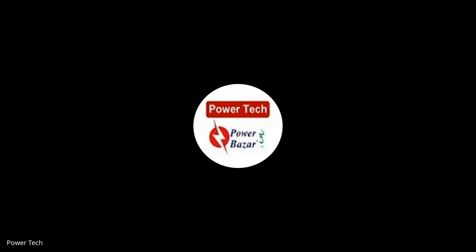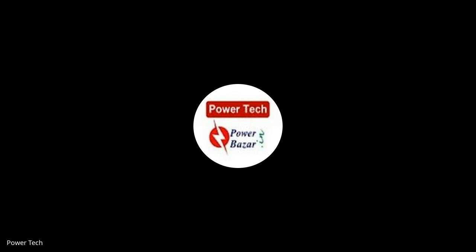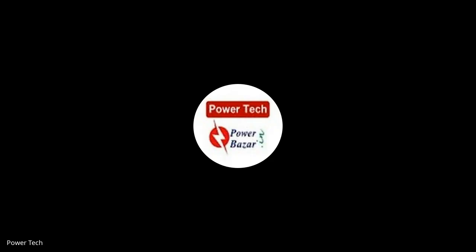Santo Mandal ji has asked, any thumb rule, how much energy do active filters consume? What is the energy consumption as a thumb rule? It is 2 to 3%. 2 to 3% of the total power they handle? The capacity, suppose we have a 500 kVA, 2 to 3% is self-consumption.